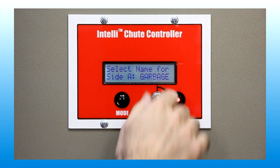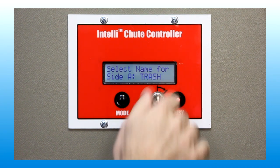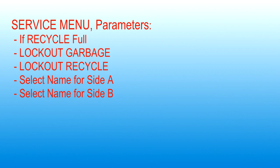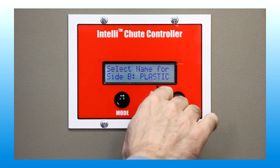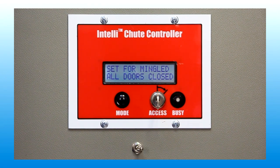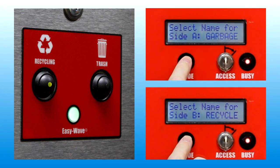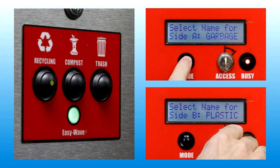The Select Name for Side A parameter provides a list of alternative waste stream label names. Changing the label name will help match user interface display messages to the type of waste material associated with Side A. The Select Name for Side B parameter operates in a similar manner and will change user interface display messages associated with Side B. For most BiSorter applications, default names garbage and recycle are typically sufficient. However, the flexibility of this feature is an advantage in other applications such as tri-sorter equipment.